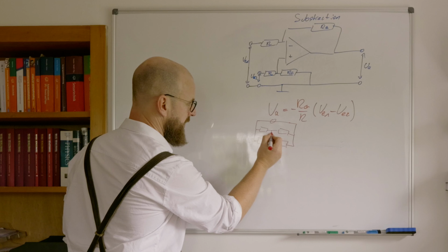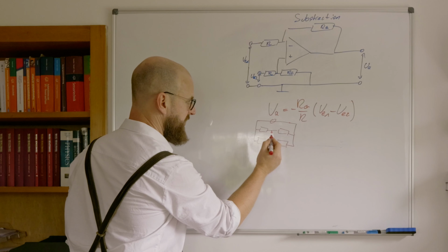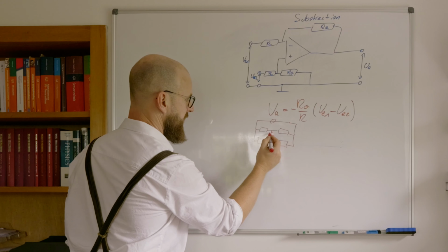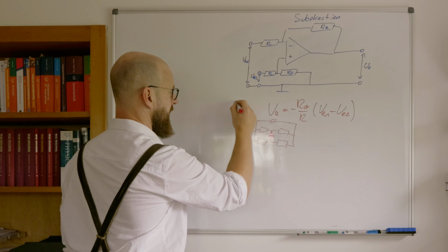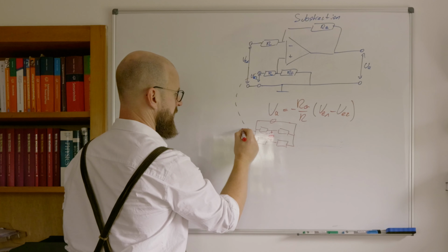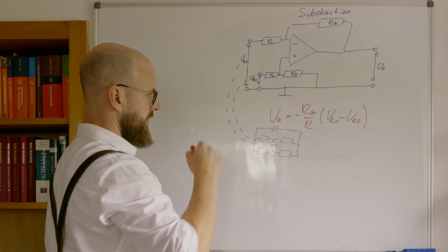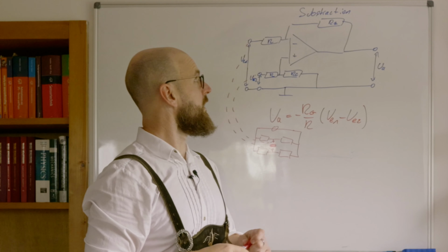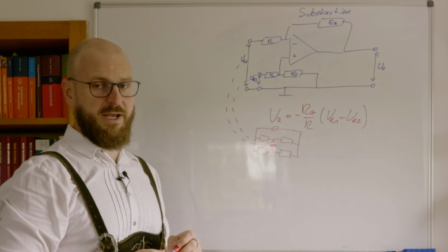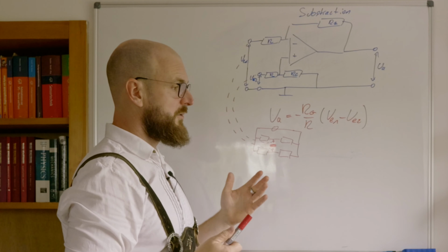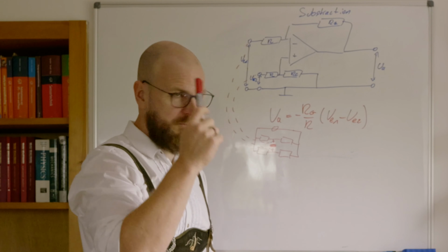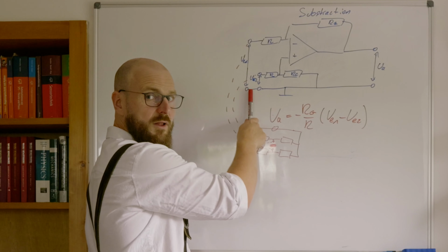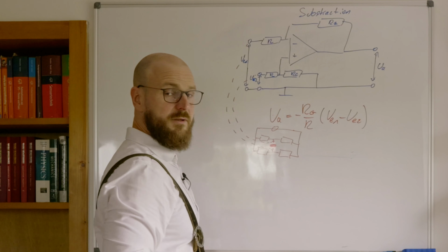And we want to measure that voltage difference within here. So for that case, we would connect the two poles to the operational amplifier system of a subtraction amplifier. Why not use some other amplifier? Remember, all those input voltages were relative to the ground.